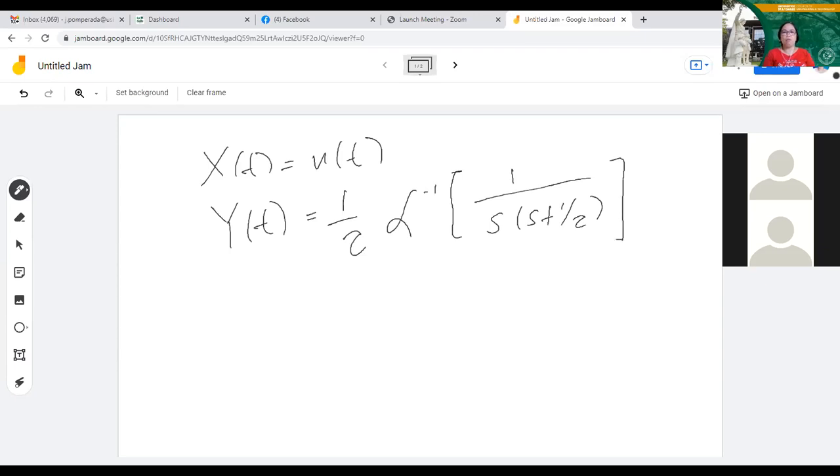So I'm asking you, what is the answer to this inverted rational expression in s that will now represent the response to this particular step or unit step forcing function? Okay, let me check. Somebody wrote in the chat box. So if I get rid of the 10, that would be 1 minus e raised to negative t over tau.